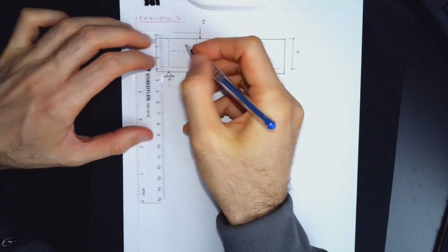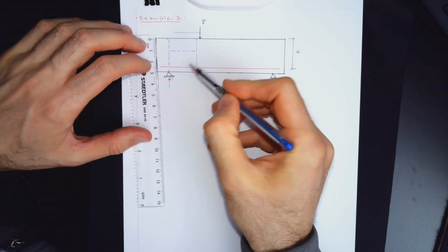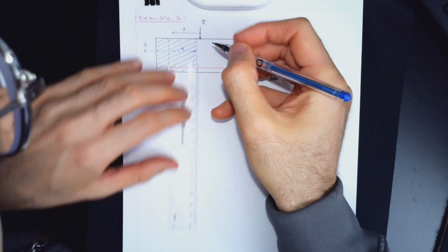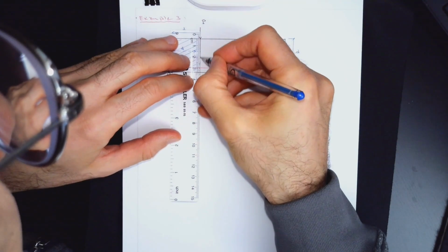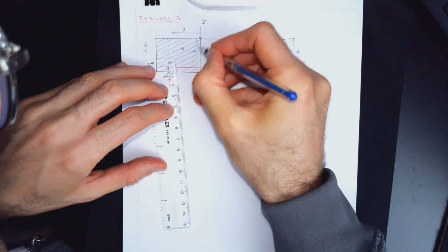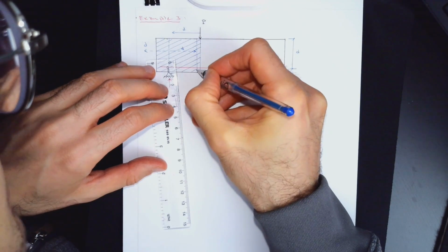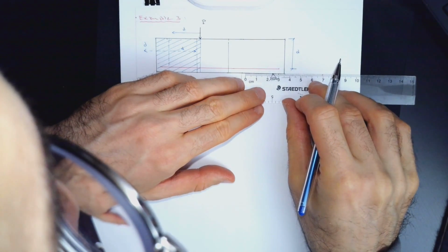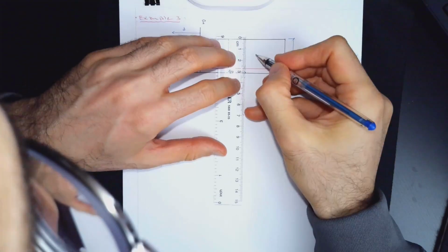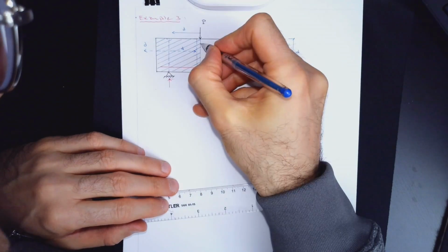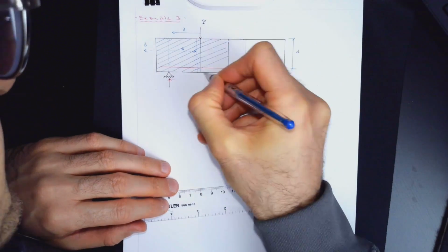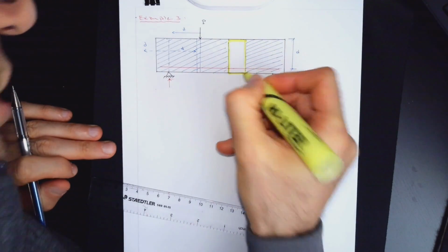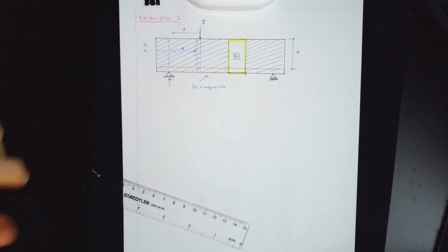This is a really significantly deep region. So it is almost 1-to-1 aspect ratio. This should really start from here. There is really no slender region. So you have to use deep beam analysis methods to design this span. If you look at this one, you would have a slender region. A little bit though, but still you can do your check shear capacity moment calculations for that region. Slender region. This is B region. The left shear span, deep member.